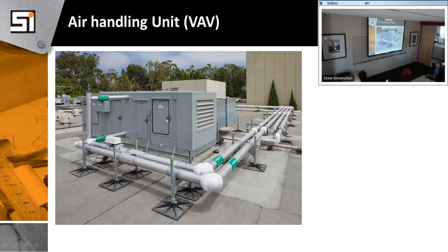So now you see all this piping running across. This is what we call an air handler. I don't have a compressor in here with refrigerant. You're not going to see any fans blowing heat, because somewhere else I generated the cold water for the evaporator. So all of a sudden, this is just a fan and a filter box with a coil, fundamentally. They could get humongous, but it's that basic. I got rid of the compressor, the condenser fans, and all the controls related to operating that. So it's a smaller box, because I don't have to have all that in there.